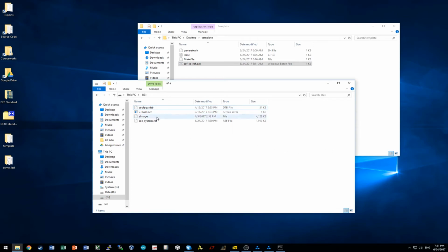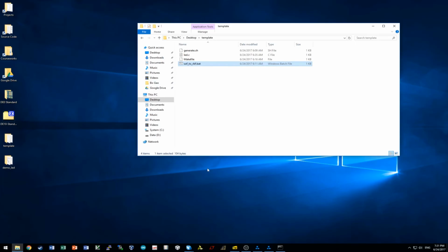Alright. This is one way we can load our bit stream to the FPGA, that's on U-boot, or as we demonstrated last time, we can use the configfs, or you can simply plug a cable into the Byte Blaster and just load the FPGA from a Quartus programmer. And that's pretty much the three major ways to do this. I will just use U-boot to help me do this. And let's boot up the FPGA. Let's see what will happen.